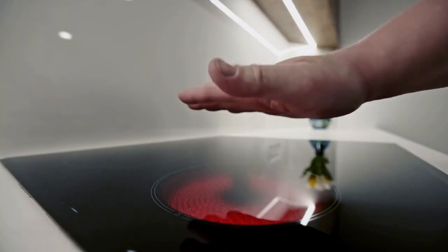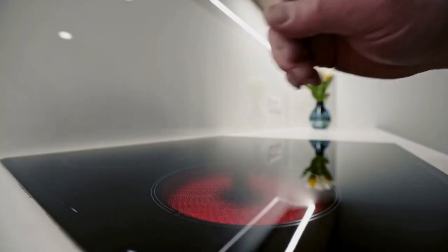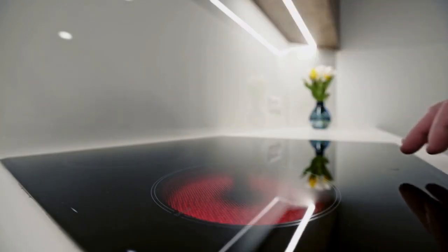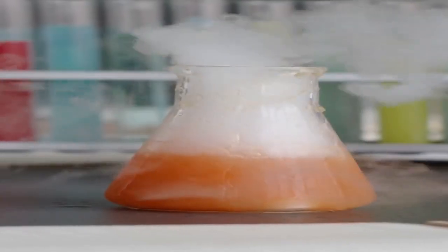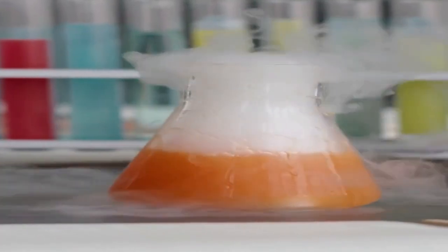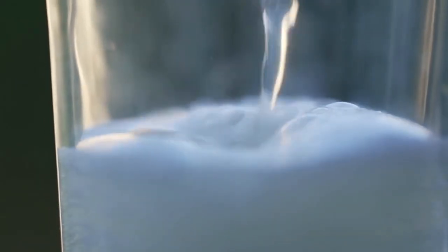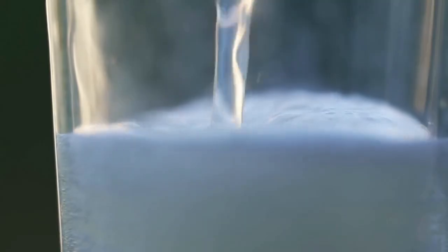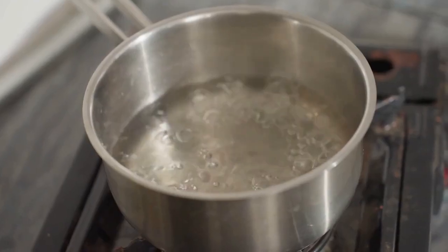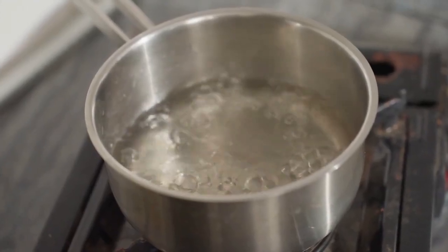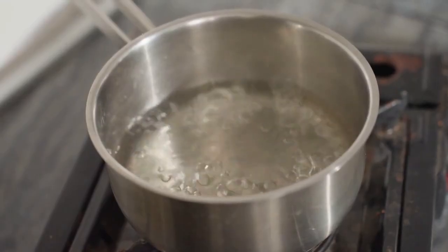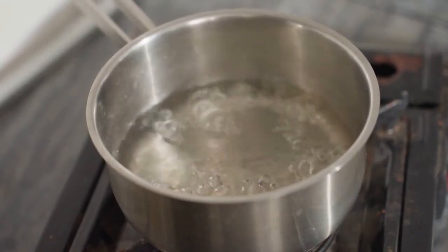Let's use a simple example, boiling water on a stove. Imagine you heat a pot of water until it reaches 100 degrees Celsius, its boiling point at standard atmospheric pressure. At this exact moment, it's a saturated liquid, and its energy content is represented by its enthalpy, Hf. If you continue to add heat from the stove, the water's temperature won't increase beyond 100 degrees. Instead, it will start to boil and turn into steam. All the energy you are adding during this boiling process is the Hfg.